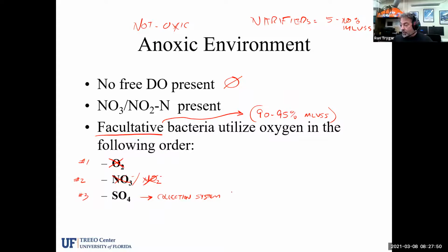And what generally occurs then is we have the production of hydrogen sulfide gas, which is generally a gas that smells like rotten eggs and causes the formation also of H2SO4. So we know that that is sulfuric acid. And so the acids that can be formed can drive the pH of the influent wastewater down and also produce acids that would eat away at concrete pipes, iron pipes that aren't protected. We can start to have degradation of the headwork structures. We can have concrete crumbling apart in manholes and the sewer systems in general.